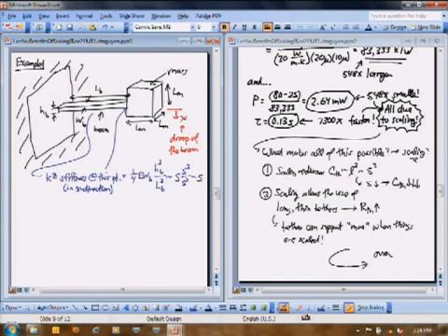Okay, but there's another side to this whole thing, and that is the mass of this thing. Right? So this whole thing here has a mass. So M is going to be our mass, and that mass is going to be equal to the density times the volume of this thing. Well, the volume of this thing is just LM cubed. Okay? And so if we want to do our scaling thing, that goes as S cubed. And so that says that as S goes down, mass goes down in a hurry. Okay, so stiffness goes down as you scale things down, but so does mass, and mass goes down a lot faster. Okay, so what's more important in the droop of this whole thing? Well, we can write an expression down for static equilibrium to get the droop.